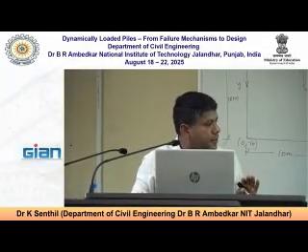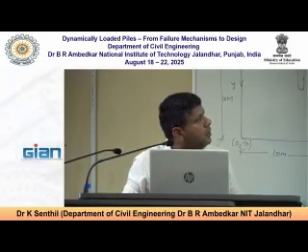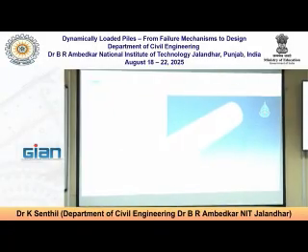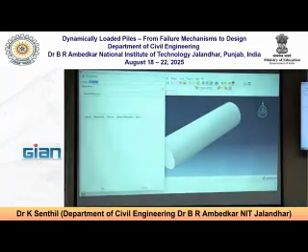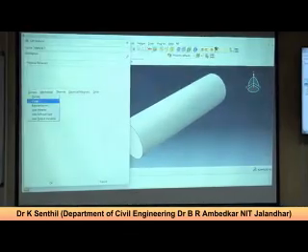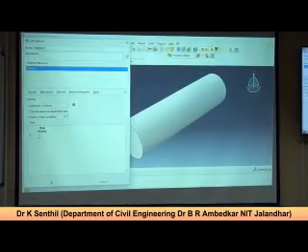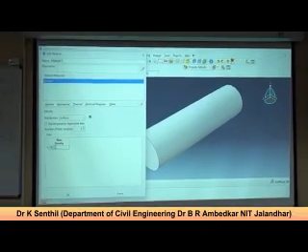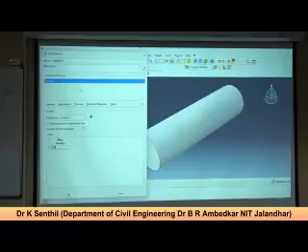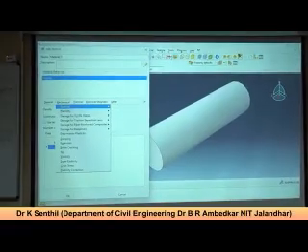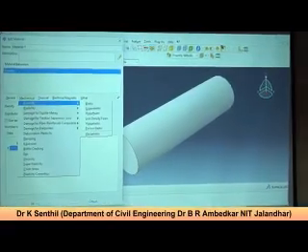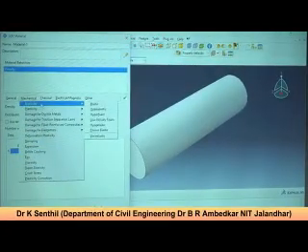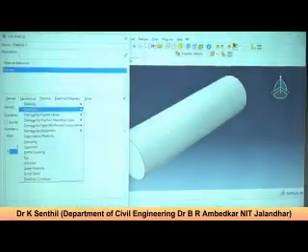You go to this. Here you have to create the material. So now let's say the density of the soil, whatever soil. Okay, what is the density? It's approximately 1850 kilogram per meter cube. And now you can see here under mechanical you can find different material parameters. Okay, you go to the plasticity.